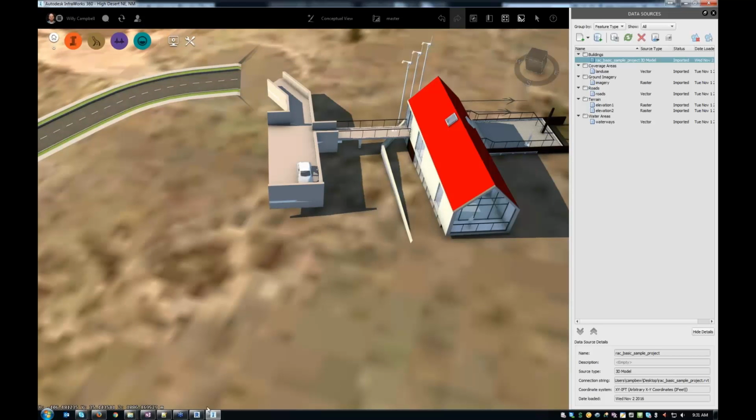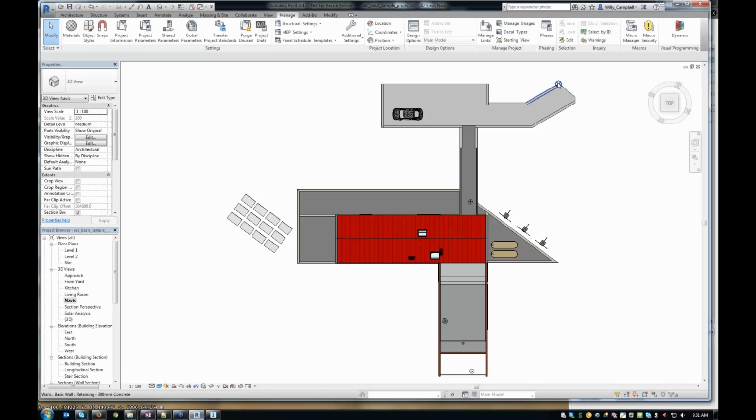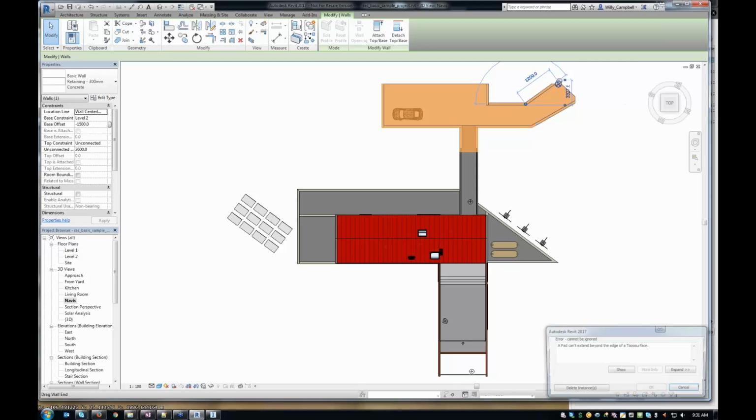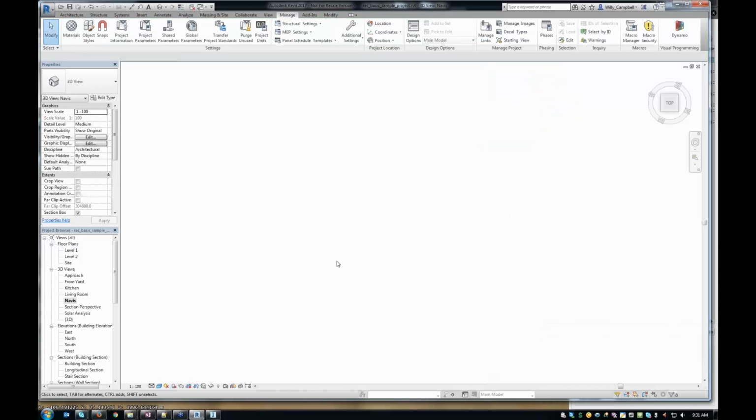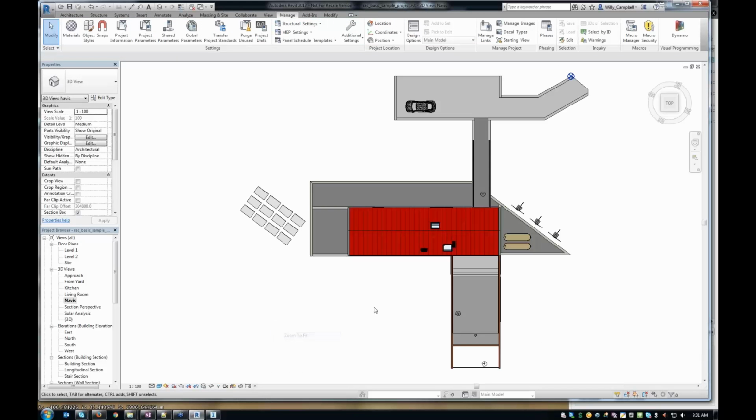And if you forget, in Revit, to reset the base point to 0, it will come in somewhere in the middle of your model, whatever those offsets happen to be. So you would need to change that before you export and save as again.